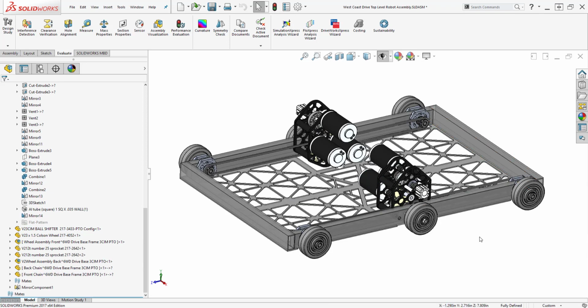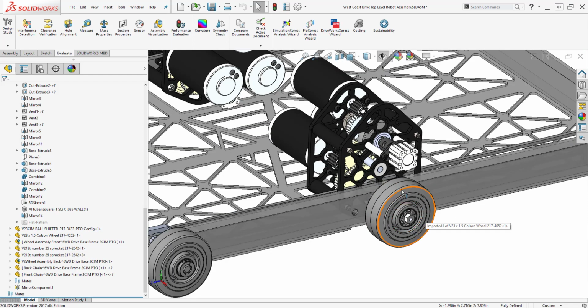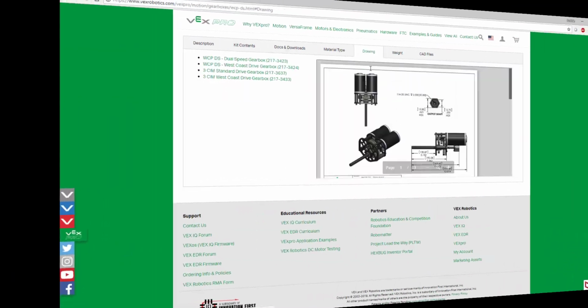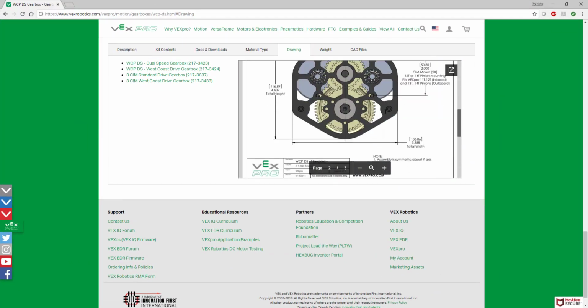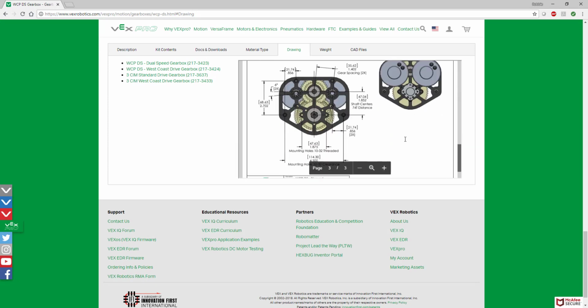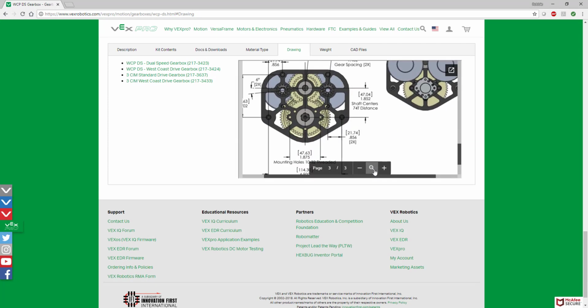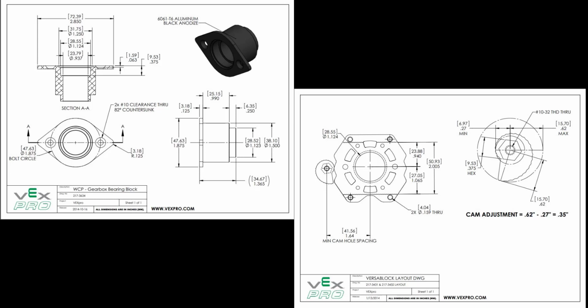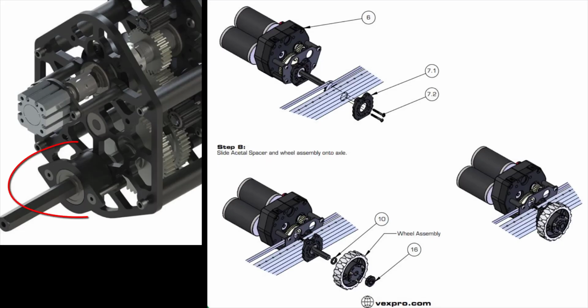Since one set of the wheels is going to be driven directly by the gearbox, we will treat the hole pattern for the gearbox as the center for the first wheel. To get the hole diagram, we can pull the drawing from the gearbox source documents on the website and find out where the holes need to be. For our West Coast Products gearbox, there are 2 ways to mount it that YETI has used. For the less precise method, we have used the sliding bearing block method, but we typically use the inserted bearing flange method because it creates a nice anti-crush zone around the gearbox mounting location.